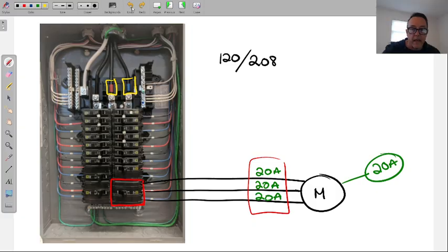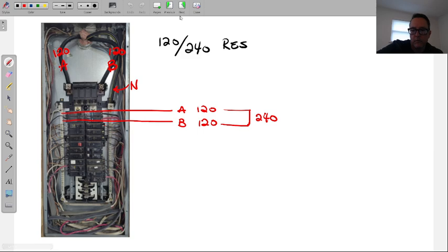Now, this is a multi-wire, more than one ungrounded conductor, multi-wire branch circuit. It's going to a load branch circuit, not another panel somewhere. So it fits all of it. It's a branch circuit, it's a multi-wire branch circuit, but it has no neutral. Going back 1, 2, I erased it all, but there's where it was. It's on video. Multi-wire branch circuit with a neutral.